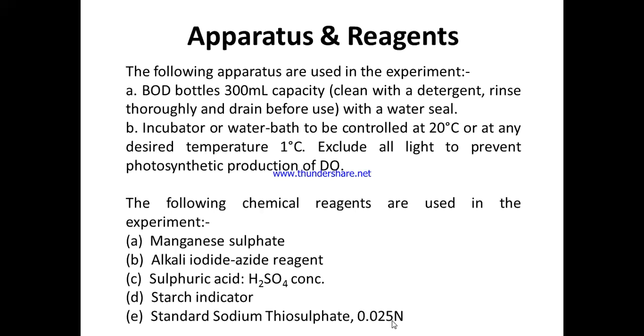Initially how much dissolved oxygen there is, finally how much dissolved oxygen, that difference just multiplied by the dilution ratio, which is the volume of diluted sample divided by the volume of undiluted sample. That is the dilution ratio. Okay, that is why you will see that all the chemical reagents are the same